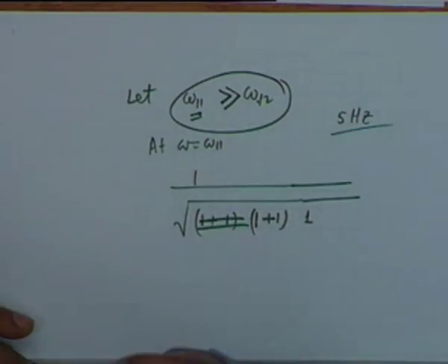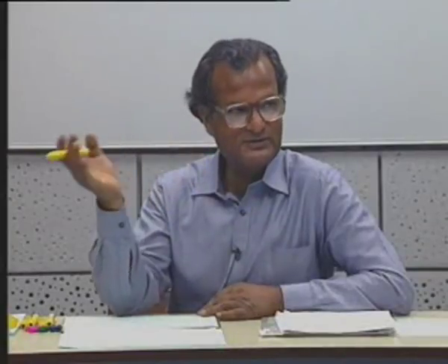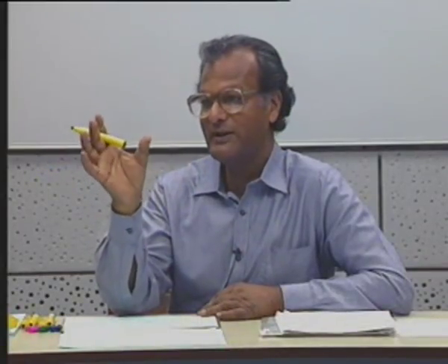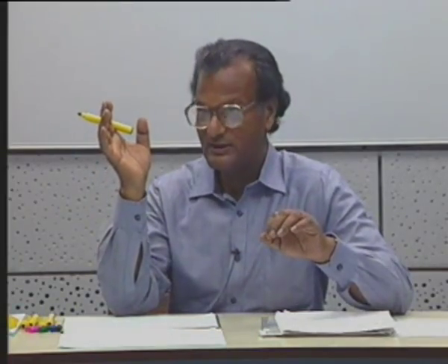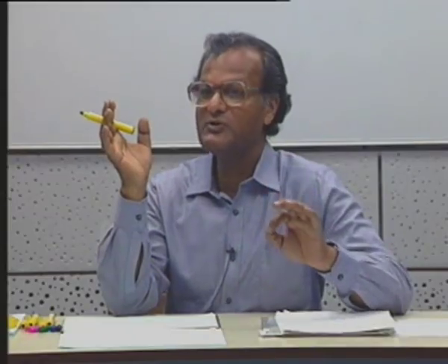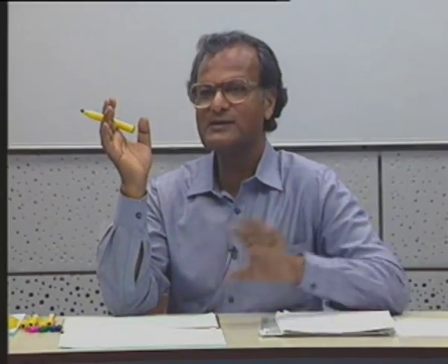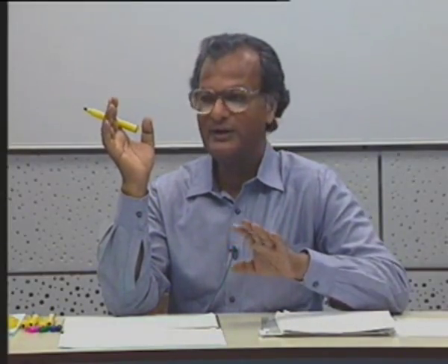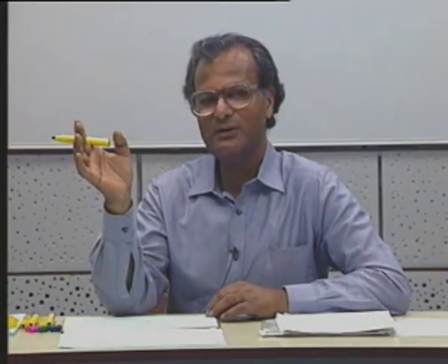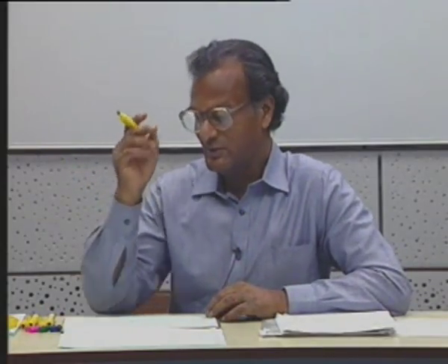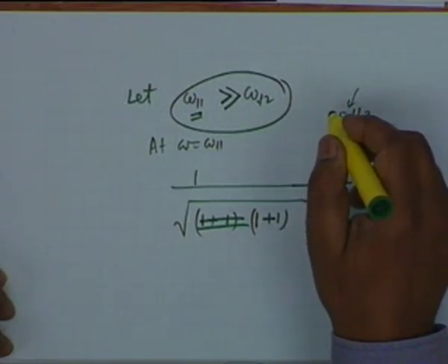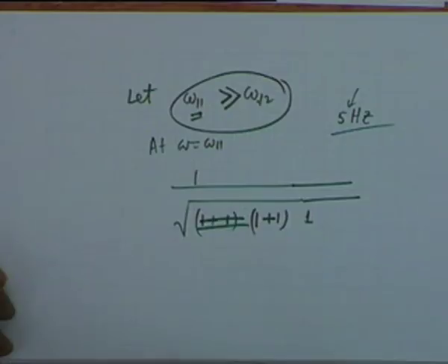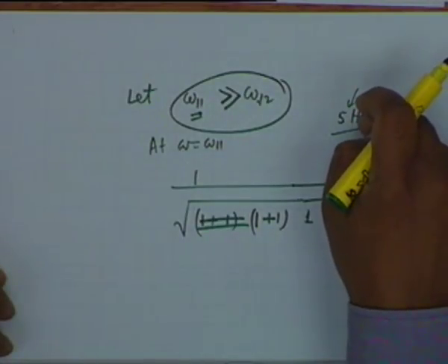You are told that audio frequencies go from 16 hertz to 16 kilohertz, but if your amplifier satisfies only this, the drums, the left-handed, the baya in particular, which is very rich in low frequency, that sound is lost. All right. If you want a very high fidelity stereo amplifier, then you must go down to about 5 hertz as the low frequency cutoff. All right. You have to design an amplifier with 5 hertz cutoff.